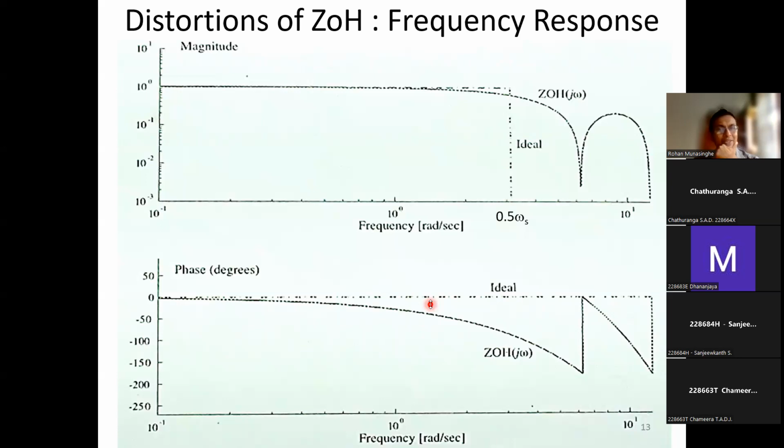Yeah, of course, yes. Because if you set a very high sampling rate, obviously you will not have any problem with your signals, right? They are not attenuated, they are not phase lagged. But the problem is, you are generating a lot of data, right? The amount of data you generate in 1 second doubles when you increase the frequency by a factor of 2.